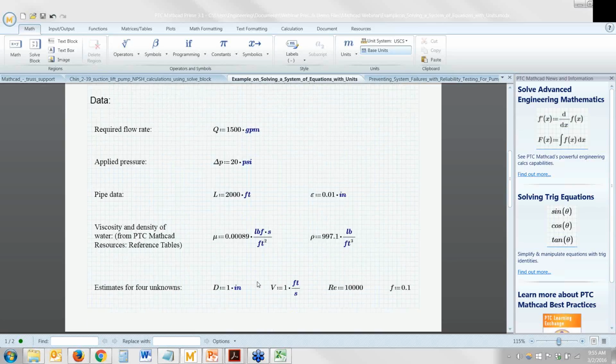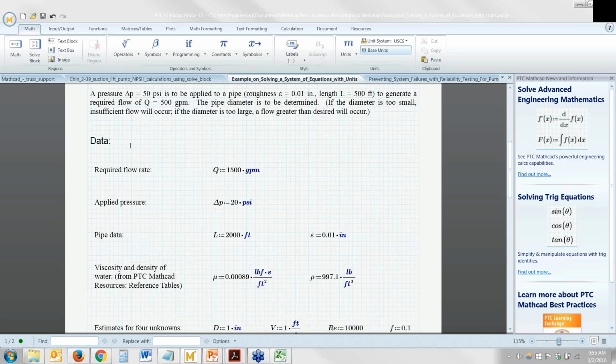But I could also come into Mathcad and say, hey, I know my length is in, actually I'll do it over here. I can come into Mathcad and say, let's add 1 yard plus 20 inches plus 50 meters, plus 1,000 millimeters. And you'll notice Mathcad understands everything I just did, and it pulls it out in feet, right?